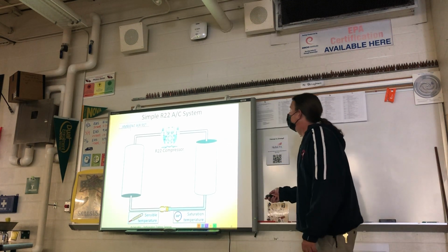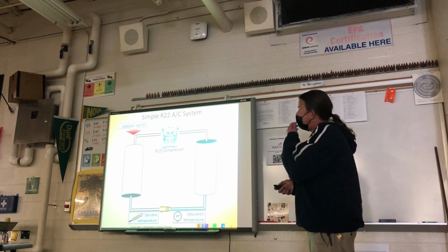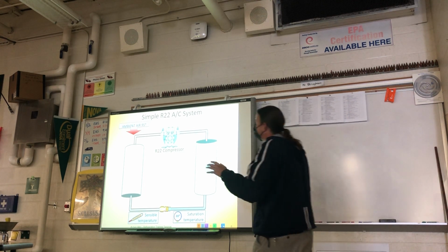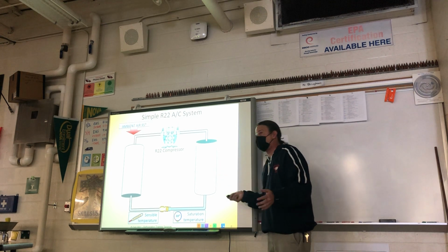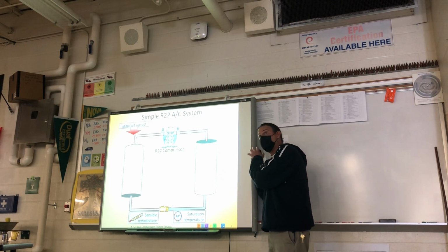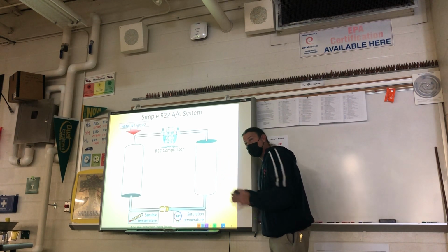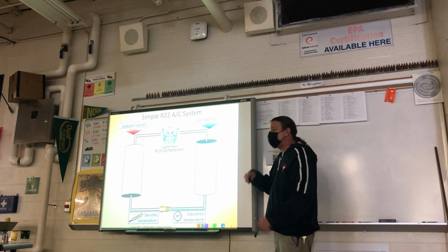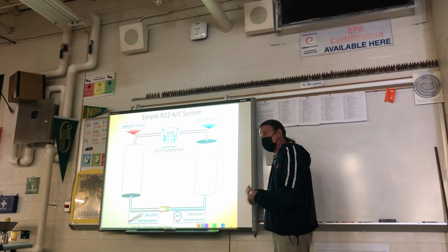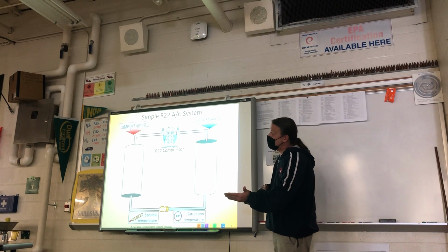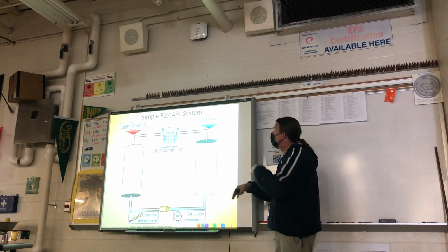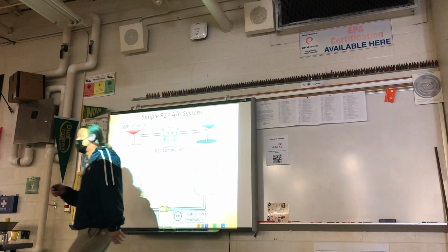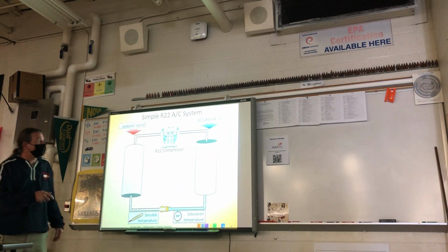So let's take a look here. You got the outdoor air 95 degrees. That's a typical summer day. It's what all the equipment manufacturers design their systems for, 95-degree day. So if it's a little hotter, it's not going to work to the exact specs. If it's a little cooler, it'll actually work a little better. But the indoor is always generally about a 75-degree national average. All right, some people keep 68, some people keep it 72, but typically for the national average, nationwide, we're going to say 75 degrees is that typical temperature.